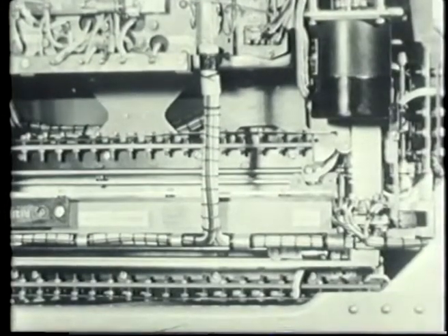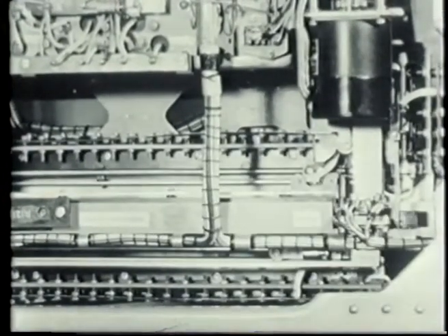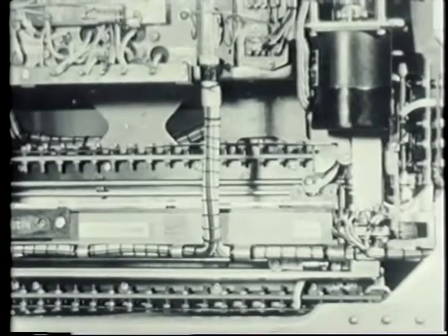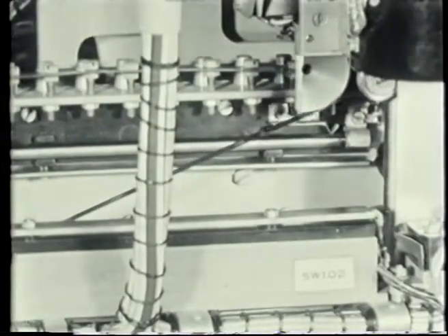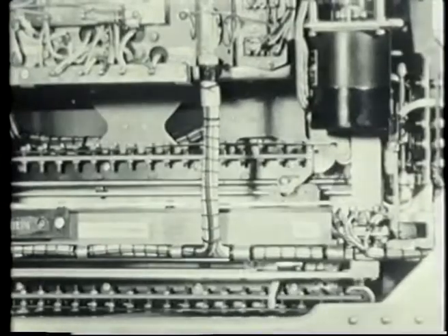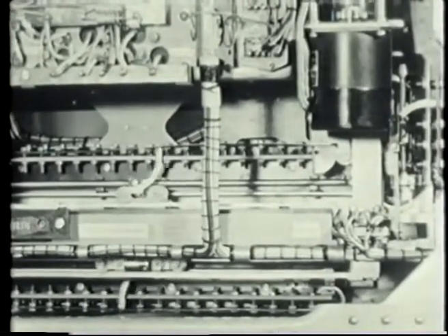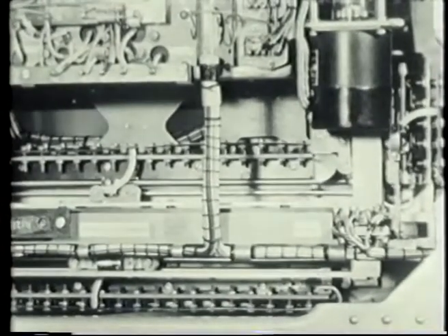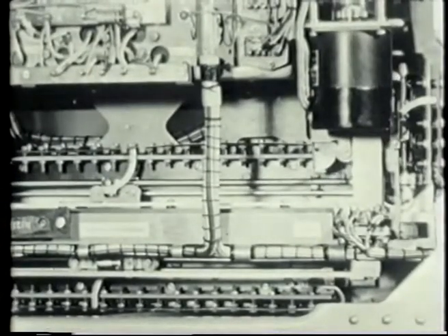To solve the triangle, two linear potentiometers are set up at right angles. These represent plan range and height. This tape, which links the sliders, represents slant range. The sliders are driven by servo mechanisms, and they continue to move until the voltage on each slider exactly balances the applied voltage. The distances along the potentiometers are then proportional to the applied plan range and height voltages.